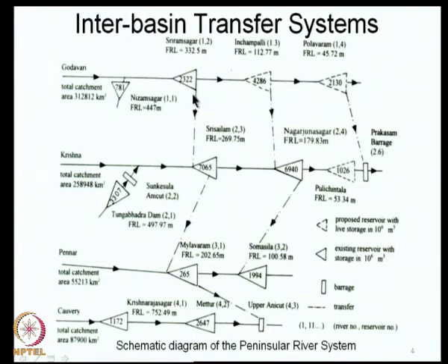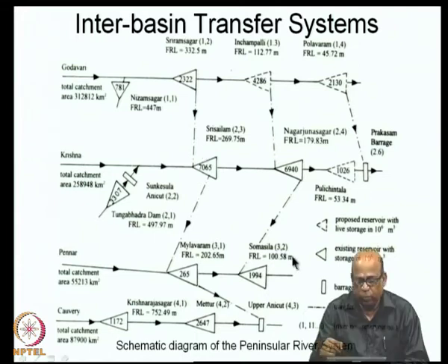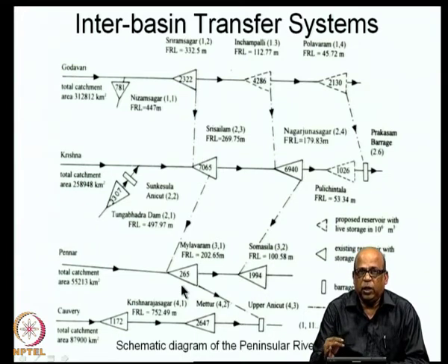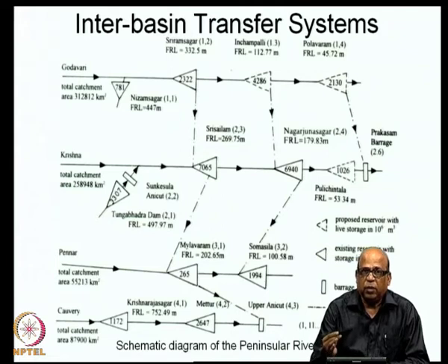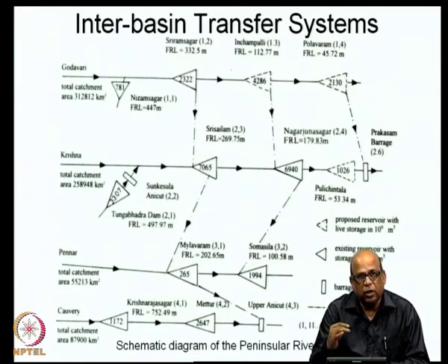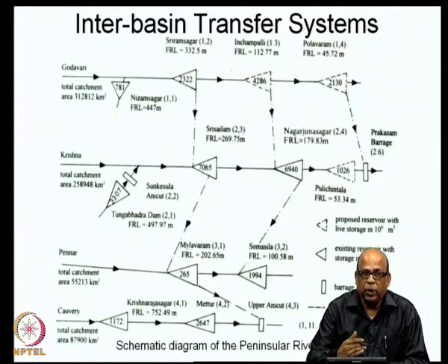I repeat, this should not be done from period to period. That is, for every time period, we should not apply this policy. But overall, when we operate this system for a long period of time, the simulation model should simulate on an annual scale. For example, annually what kind of transfer is possible, annually what kind of deficit is possible. In large systems, the time frame of analysis also should be large. You may typically look at a 50-year sequence, 100-year sequence, etc.